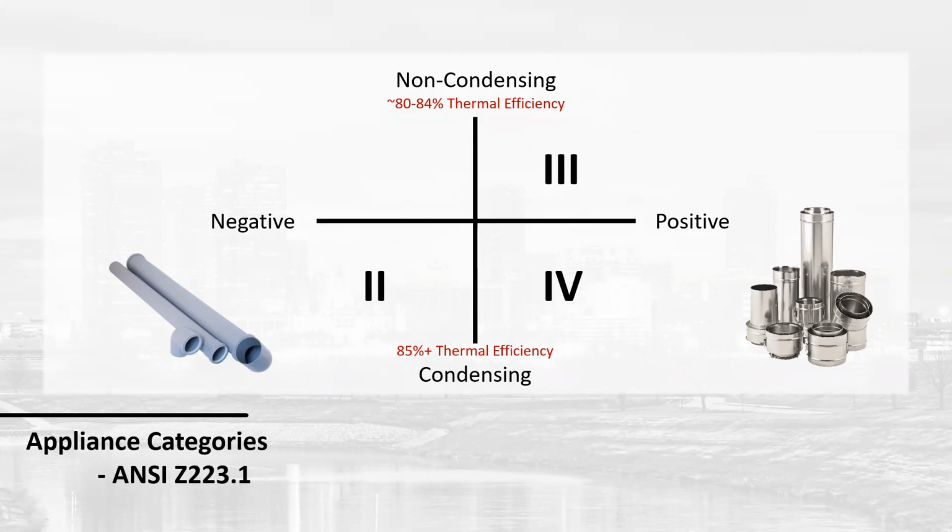One product I have not mentioned is PVC. PVC is not a UL listed product for venting. The way that they do get approved for venting is that it's approved by the boiler manufacturer itself. So it's actually part of the packaged installation approval rather than the actual product itself. So in order to get that, though, they do not have to pass that 1738.